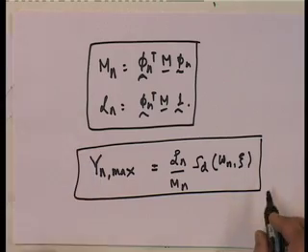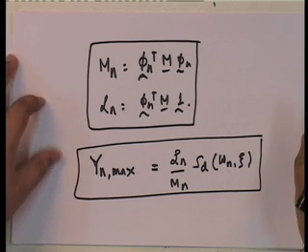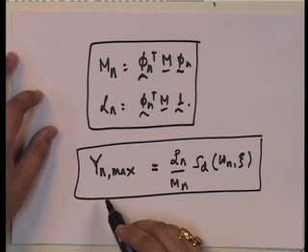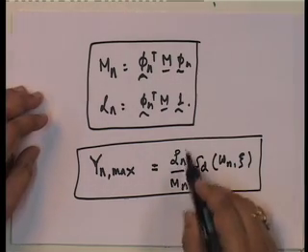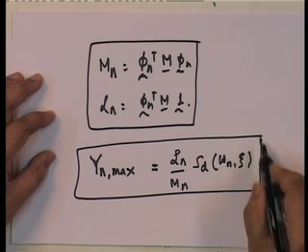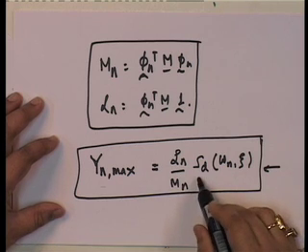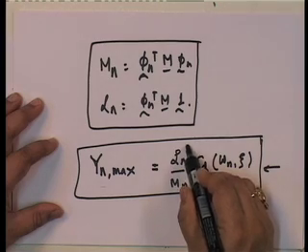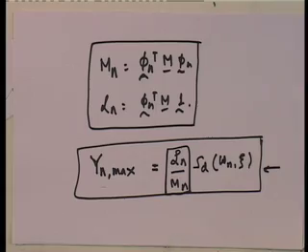Okay. In terms of the displacement spectrum, your yn is equal to what? Ln upon Mn into Sd, because in the previous case we had said that V max was equal to Sd. Since this is being multiplied by Ln upon Mn, that factor simply continues. So I can get the maximum modal amplitude in terms of the deformation spectrum. The only thing is the deformation spectrum is now multiplied by a particular additional term.